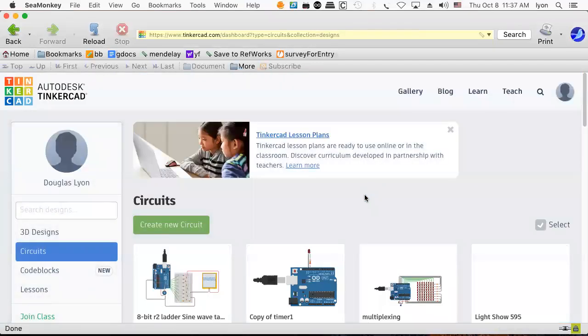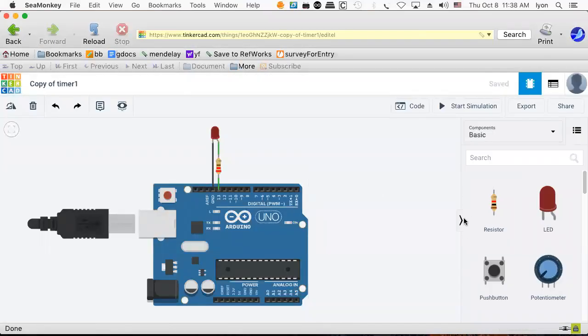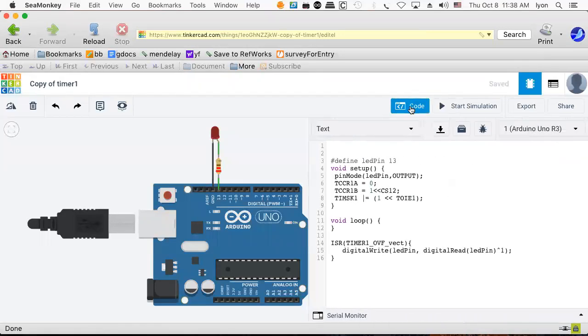Because we want to program our timers to blink and do things and whatever. So here's the blinky light, right? We've done the blinky light before. We're going to do it again, only with a difference. And the difference is we're going to go into the timer control register, right? And so now with the timer control register, using timer 1, we have a 16-bit register with timer enable.